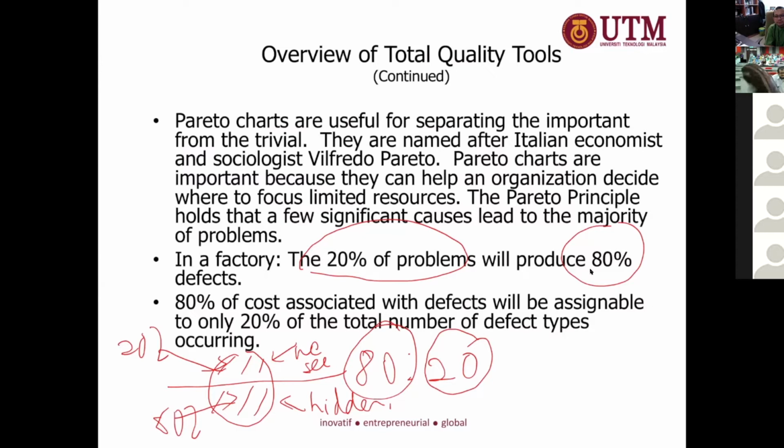When the timing belt breaks, it is like a stroke. People get a stroke. All the components inside the engine become uncontrollable. The purpose of the timing belt is to control the timing of your valves. So when the timing belt breaks, the valves are uncontrollable. The valve will fall down and hit the piston head. So it costs a lot for the overhaul. Instead of saving 40 ringgit, you might spend 3,000 ringgit for a new or second-hand engine. Or if you want to do an overhaul instead of changing the engine, it also costs you a few thousand. That's the 80% when the timing belt breaks.